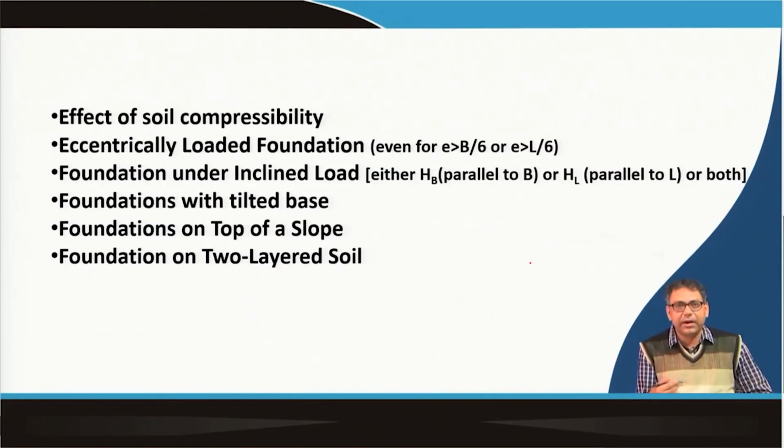So, now the next part that I will discuss, because in this advanced foundation engineering course, these are the things which are normally not discussed in our UG level core foundation engineering course, because this course is also a UG level course. UG students can take this course. So, these are the effect of soil compressibility, and eccentrically loaded foundation, even for e equal to or greater than B by 6 or L by 6.